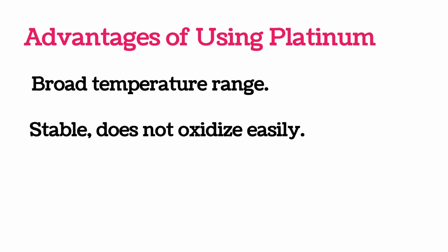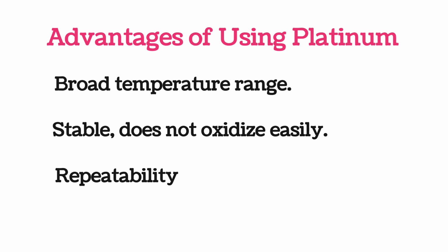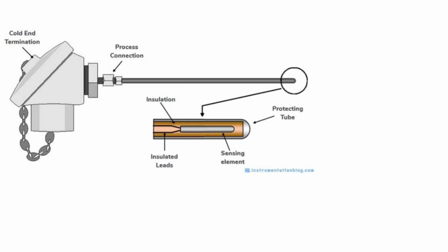That is, it cannot react with any gas or liquid to create a hazardous situation. It has very good repeatability, which means for a fixed temperature point, it will repeat the same resistance value any number of times. So, finally, because of its advantages, platinum is finalized to construct the RTD.